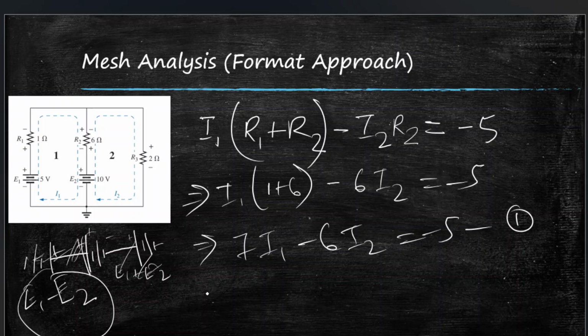Okay. Equation 2, we'll do the same thing, but first we place I1, it'll be easier, but make sure it's negative. Why? Because we're doing loop 2. For loop 2, I1 will be negative, and for loop 1, as you saw here, I2 was negative. I1, and then place the resistor that was being shared between both loops, so R2, 6 ohm. Put the value directly, 6, so basically 6 I1, and then put a plus.